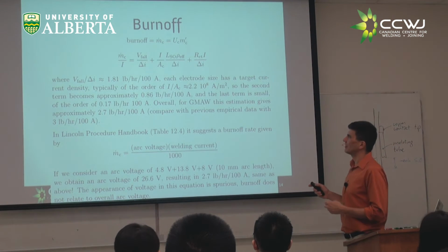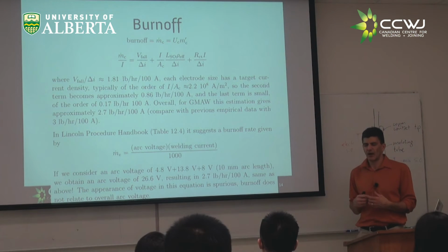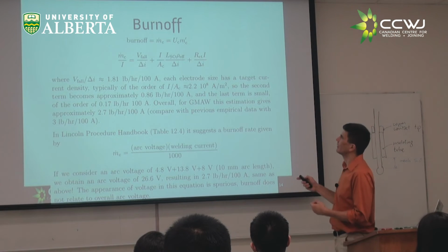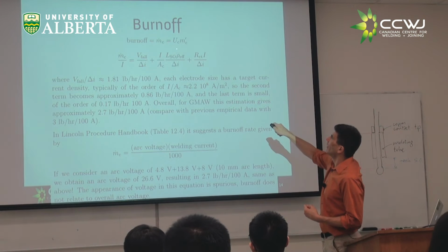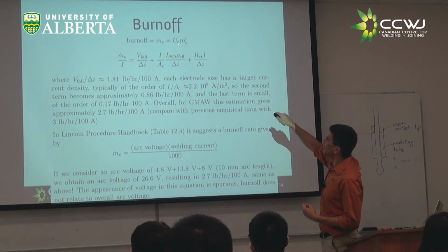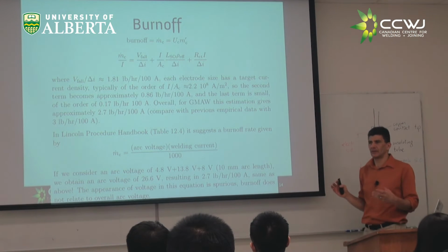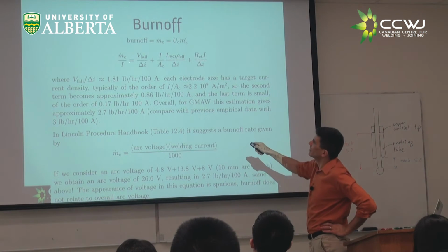There's another concept, the concept of burn off or melt off, right? How many pounds an hour does the welder burn, or can your machine do? And this is pounds an hour, right? It's wire feed speed times the linear density of the wire. That's very simple. And because we have a formula, we would get this.